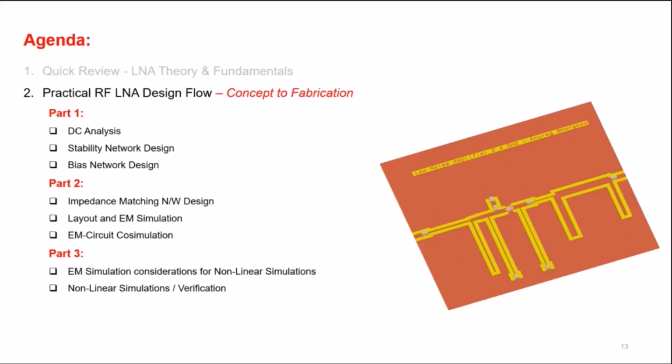I'm working on high-speed communication, wide bandwidth up to 10 gigahertz, a transimpedance amplifier, but facing a problem of impedance. Yeah, that's a very specific question. You need to connect with the local team, let them see your design, and they can offer some suggestions. There may be some clever techniques to do that. CPW to die pad wire bonding, all those things can be characterized using the 3D EM simulator inside ADS.